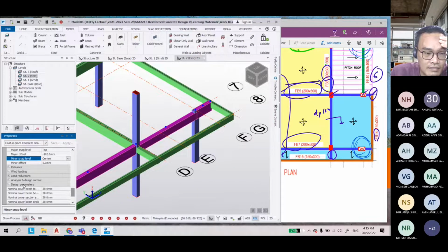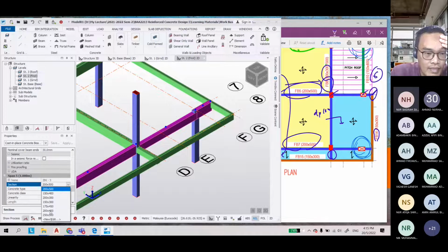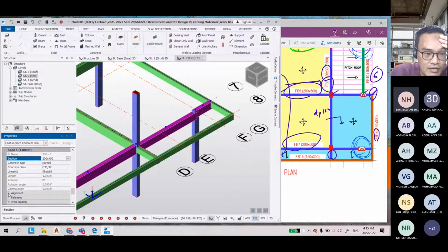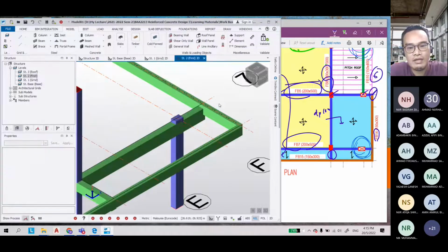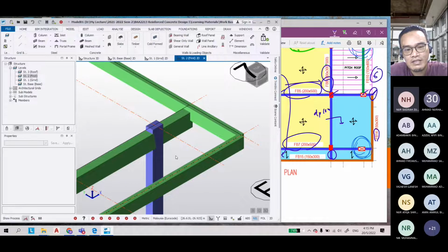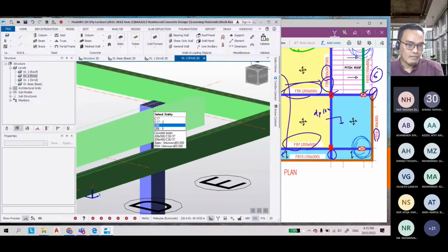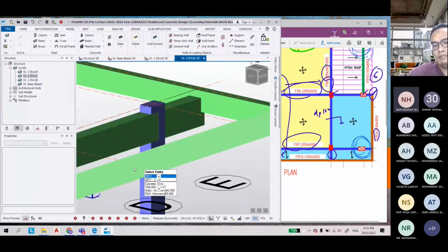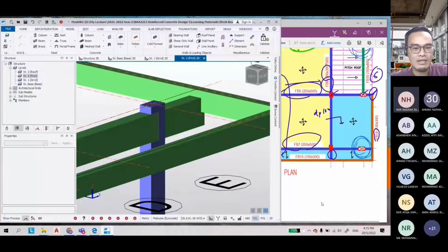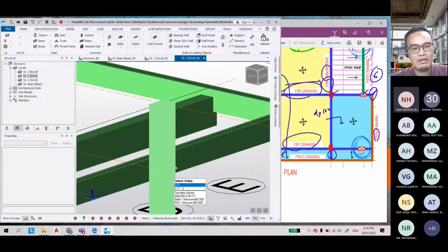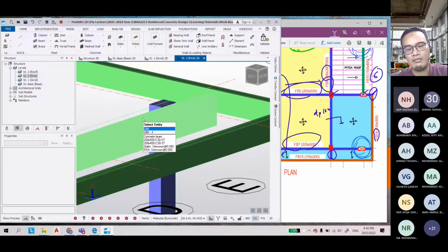and then the span number 5, 200 times 400 also the size, and then the alignment is by negative 100. Okay, also drop. Okay, you can see the column here, but it's never mind. For analysis, it's allowed, but for construction, then we can omit. Okay, the drawing, I mean they will understand. They should understand the drawing, because the level is up to there.